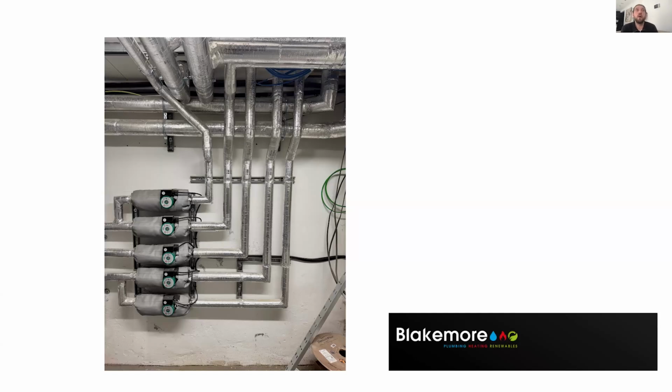For expansion, we've got 100 litres on the heating. It's designed at 45 degrees, but we've been running it at 40. What we've also got, through his Kinetic system, is load shifting, so we can load the buffer up to 60, 65 degrees. Then I've got a fixed blending valve on the secondary side, an L-Technic high flow one, which I've set to 45 degrees. So if we store higher at lower tariff times, we're able to utilize more storage out of there because we're blending down.